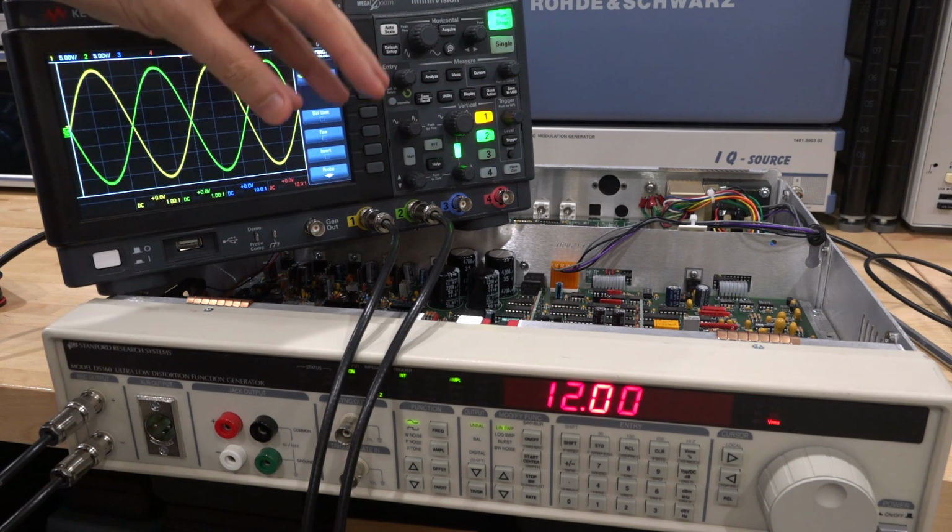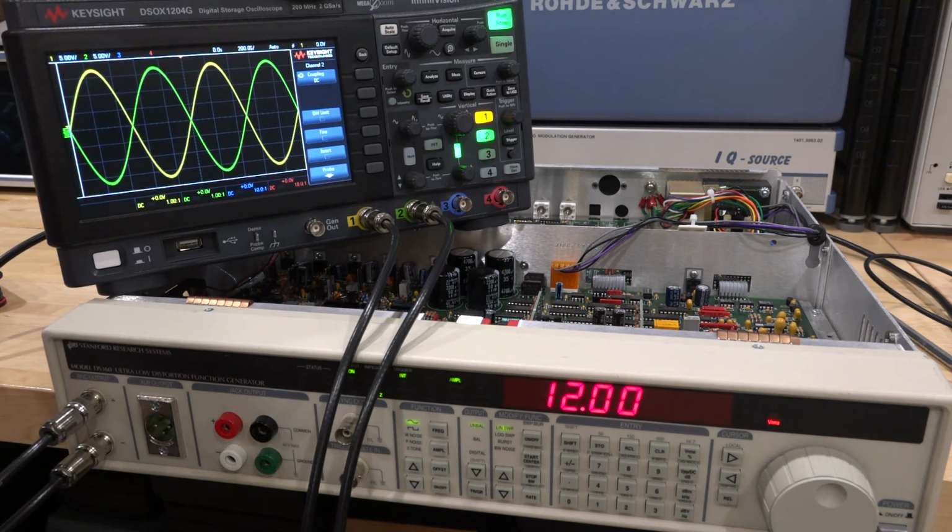Now, there was some heating, as I said, over there. Now that's gone. I can look at it with the thermal camera and things are within reasonable temperature now. But because it heated up so much, now I'm a little bit worried that perhaps there has been some damage to those components, and you cannot tell that by looking at this waveform. If you want to measure 100, 110 dB of THD, you cannot do it on this oscilloscope.